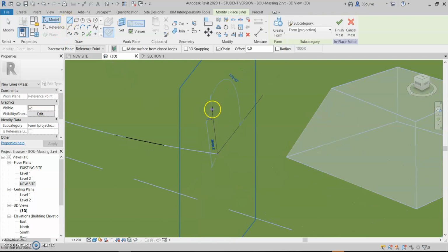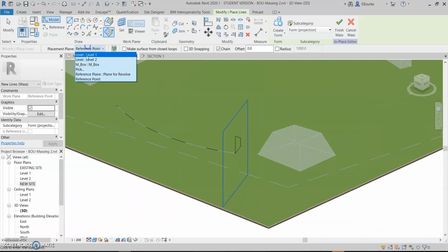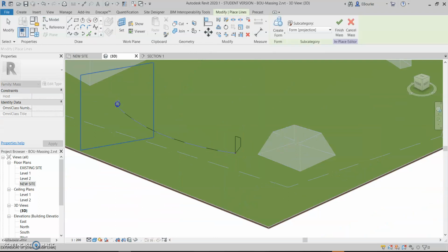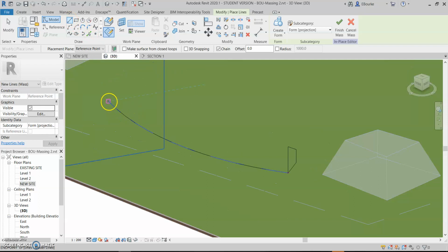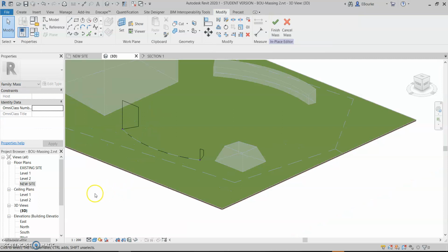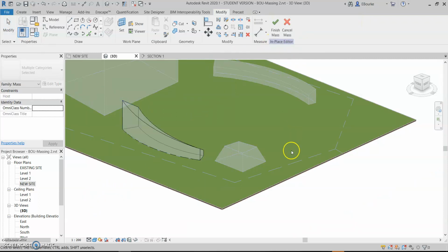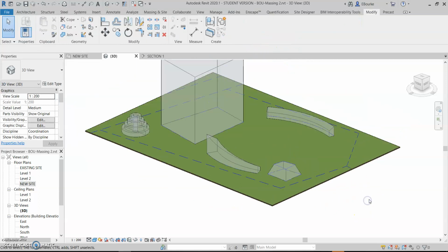So I'll come up reasonably short at this side. You just want to make sure that it's easy to tell the difference between the two shapes you're drawing. And now I'm going to pick my point at the other end, and I'll draw a taller, wider one up here so it's easy to tell. It doesn't have to be the same amount of faces and edges. I just chose to do that this time. So once I've drawn my profile at each end, my curve and my points, I select everything and create a solid form, and now I have a swept blend.